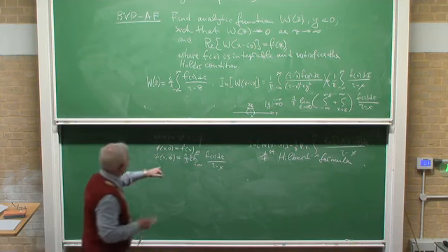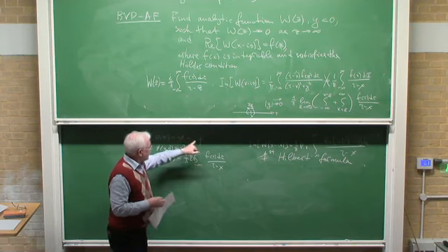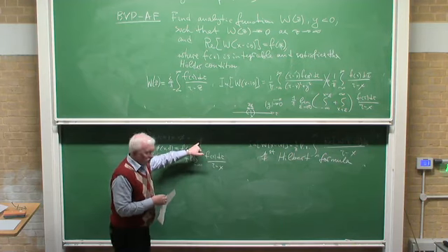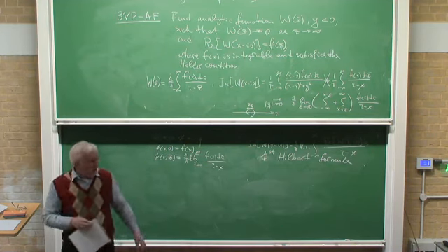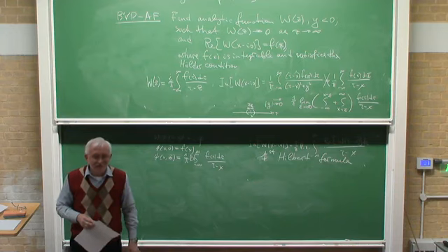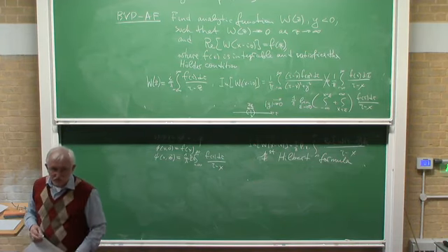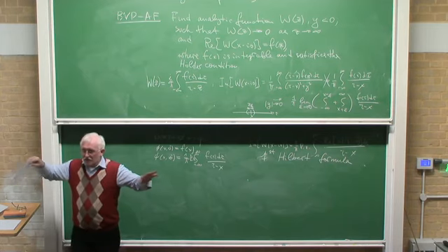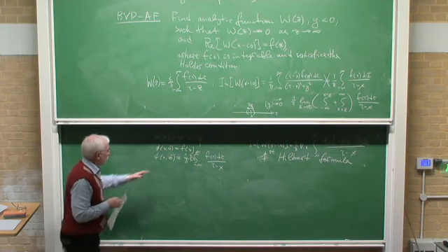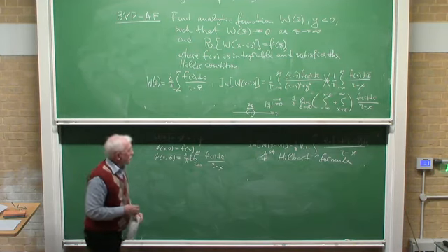You find only the real part, and then by using that relation, without solving any problem but just calculating that integral, you find the imaginary part. The real part gives you the so-called added masses as a function of frequency, and the imaginary part gives you the so-called hydrodynamic damping coefficients, which explain how much energy is taken by gravity waves radiated to infinity. So that is the formula, which is valid for any problem.